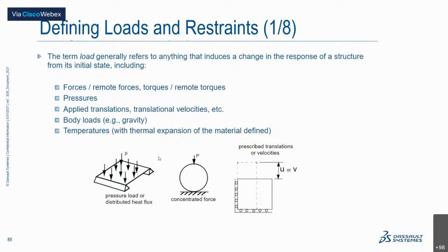So now once you have defined your materials, your mesh properties, your solid sections, and you've also seen the procedure followed to apply all of this, we can move on to defining loads and restraints. In order for a simulation to work seamlessly, you will have to define the loads and restraints. Loads are basically something that induces change in the model when applied on it for a given amount of time.